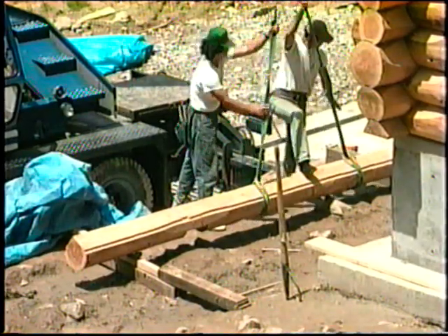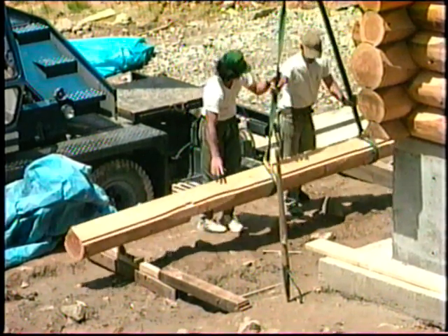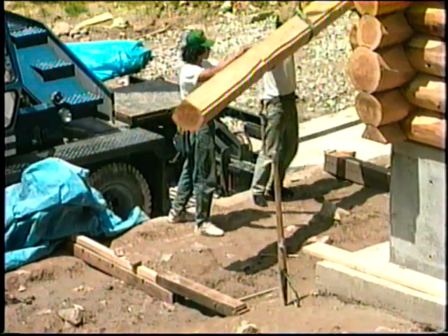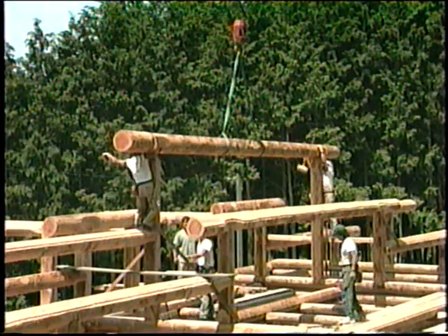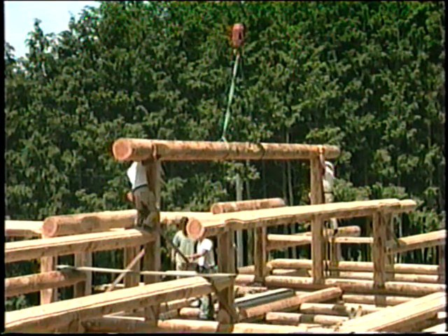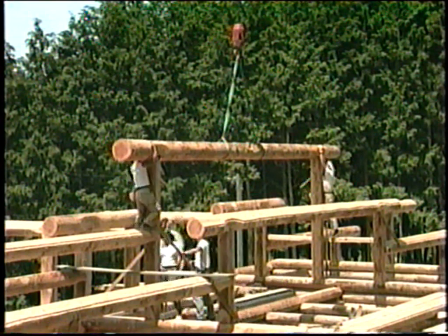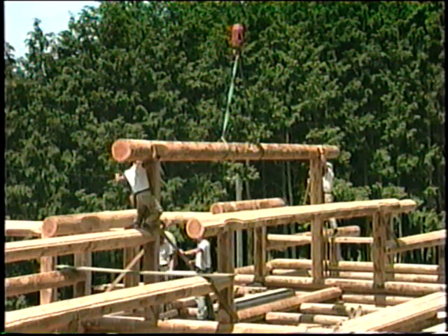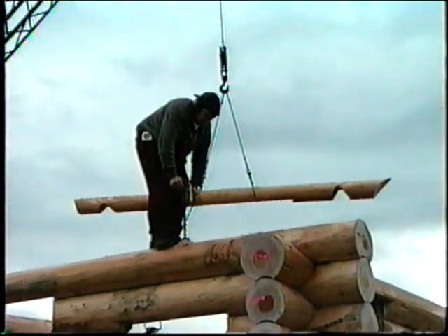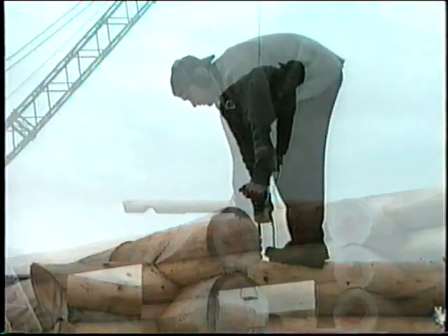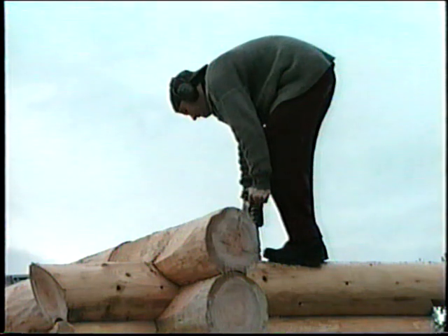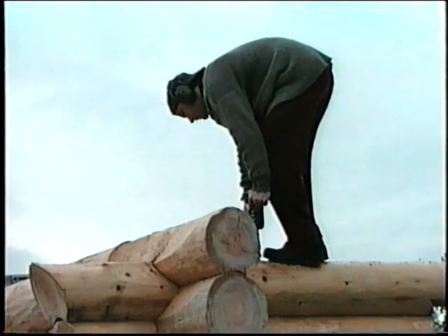Use slings or straps that are shackled to the lift hook so that there is no danger of losing the ridge piece. When this assembly is in its permanent position, the plate logs and cap logs will be drilled and drift pins driven into the next 2 rounds of logs.